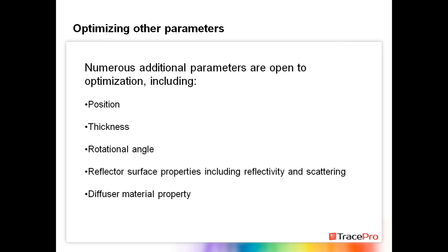And I won't run through a video here, but I'll just show the final results. Here's our optimization log and trend chart. Basically, in this case, an 8-degree Gaussian half angle produced the best results. So I could then take that information and find somebody who's producing a diffuser like that, or have a diffuser like that made. So we could use this optimization process to also generate a specification that we could then send out to have a diffuser designed or purchased.